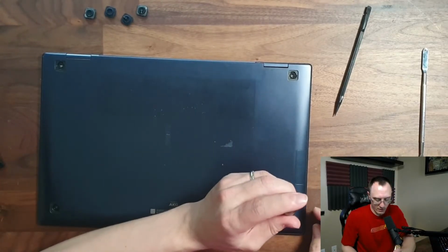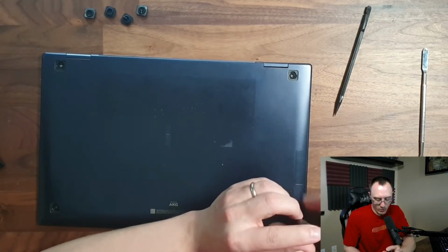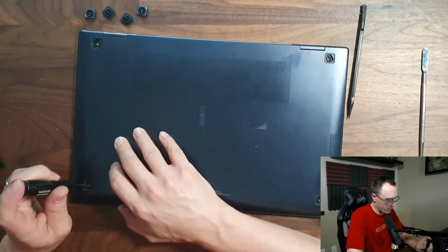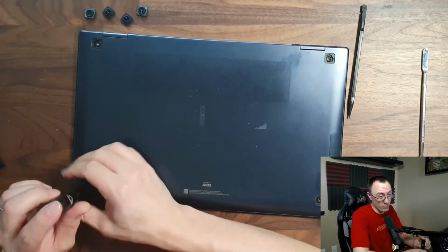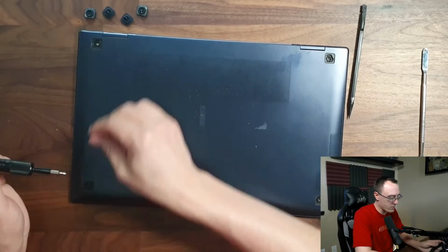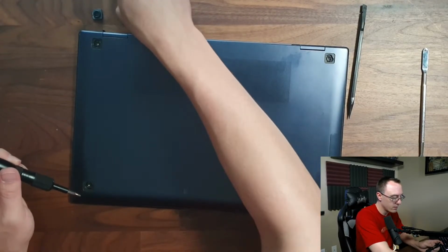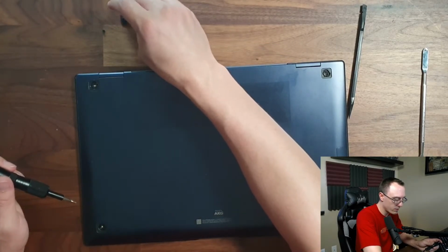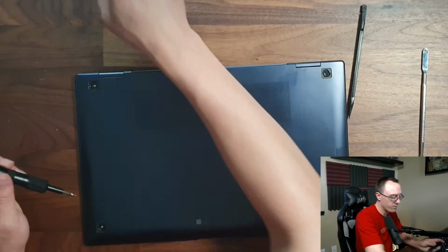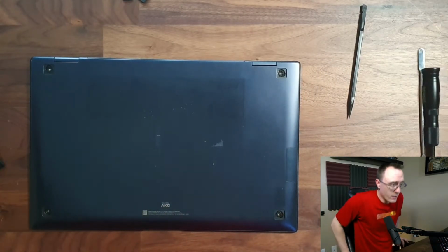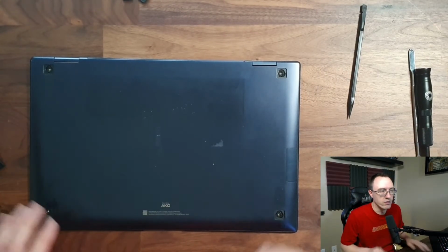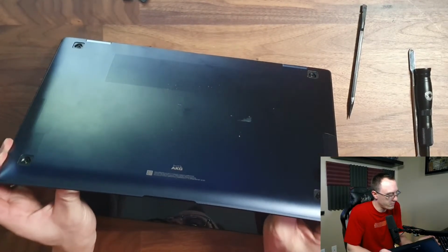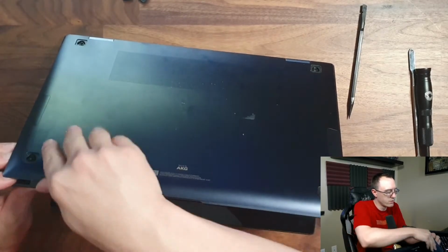And these screws are all the same screw, so you don't have to pay attention to which one goes where. But when you open up some laptops, you do want to pay attention to the screws and where they go, because some are longer than others and some are thicker than others. You can usually get a screw to go where you want it to go, but it doesn't always guarantee that it's not going to break something in the process. Did I lose a screw? No. Right there. So with those 4 screws removed, the laptop should open relatively easily. Just open it up a little bit, give a little bit of external force, pop it on out.